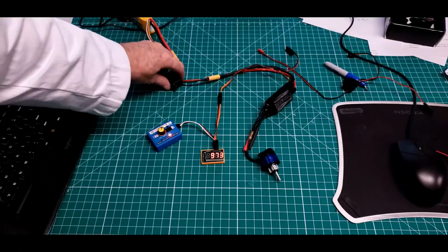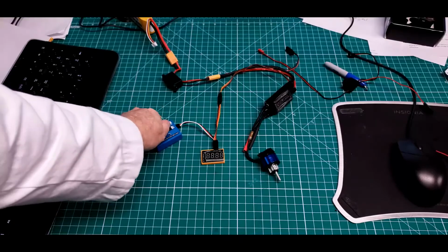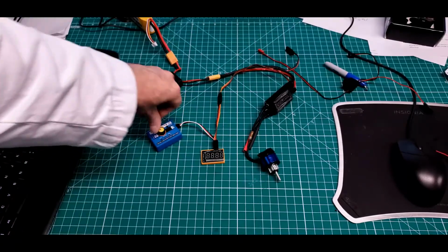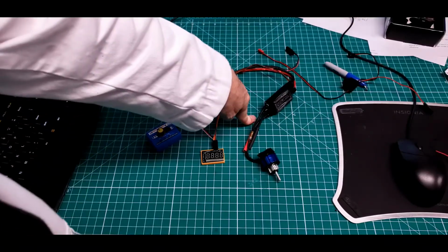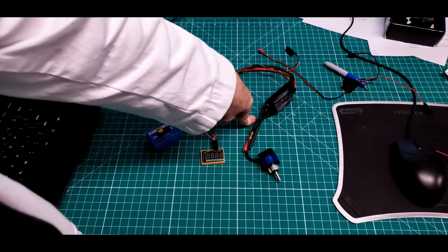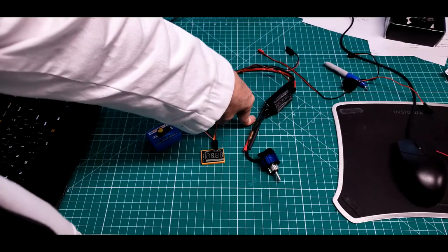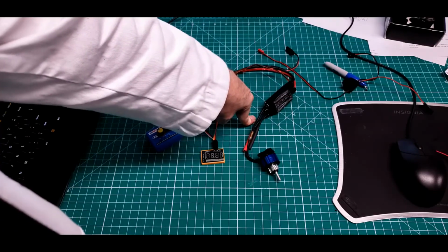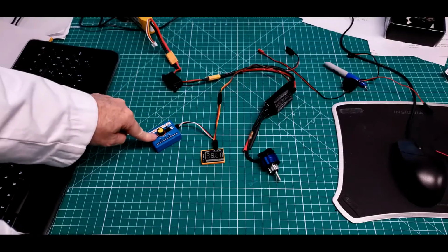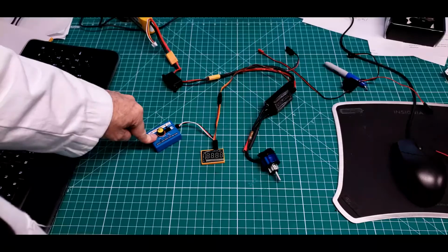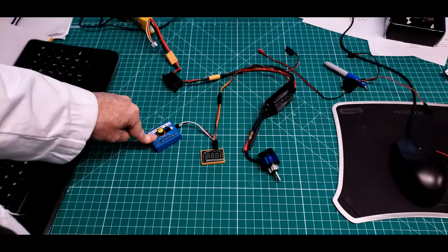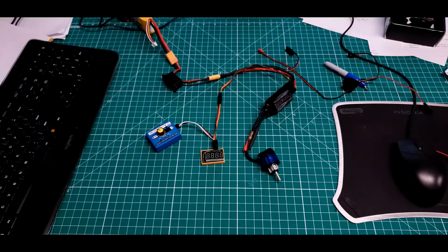I'm going to act like I've turned off my battery, put my transmitter throttle all the way up, and then I turn the battery on. When the ESC signals me that it knows the high number that it's ever going to see out of my electronics, then I will put the pulse width to the lowest number it will ever see out of my particular electronics, and then it should be calibrated. I haven't tried this, but let's see what happens here.